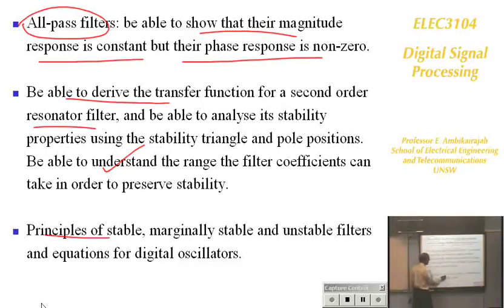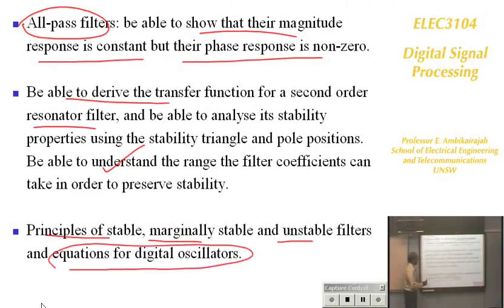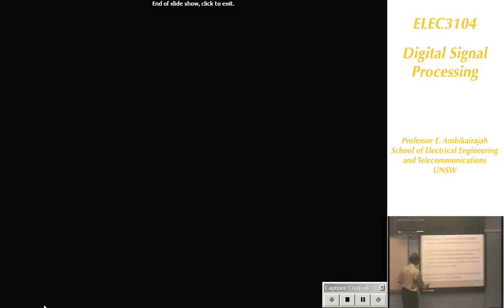Then you look at the principle of stability, marginally stable and unstable filters, and the equation of digital oscillators. How do you derive the equation of a digital oscillator, and how the initial conditions are to be set up in order to get the oscillation running.